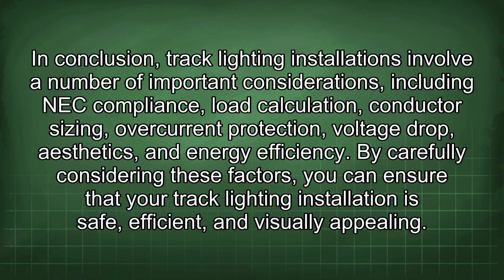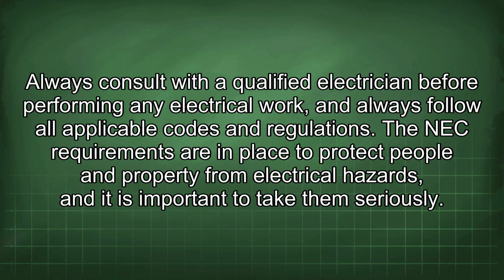In conclusion, track lighting installations involve a number of important considerations, including NEC compliance, load calculation, conductor sizing, overcurrent protection, voltage drop, aesthetics, and energy efficiency. By carefully considering these factors, you can ensure that your track lighting installation is safe, efficient, and visually appealing. Always consult with a qualified electrician before performing any electrical work, and always follow all applicable codes and regulations.